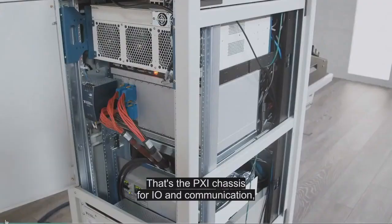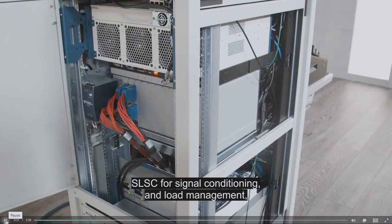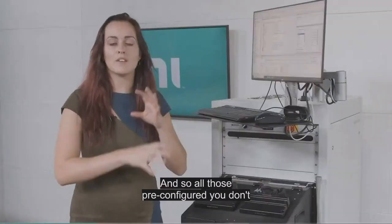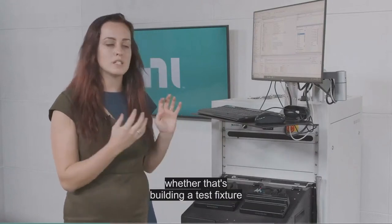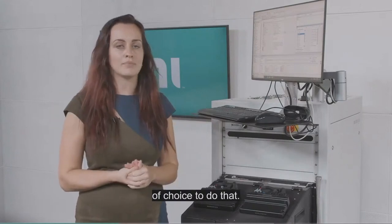That's a PXI chassis for I/O and communication, SLC for signal conditioning and load management and e-loads, and also a Virginia Panel MAX interconnect. All of that's pre-configured. You don't have to spend time doing that. You can spend time on what differentiates you, whether that's building the test fixture or writing the test sequence or getting your integrator of choice to do that.